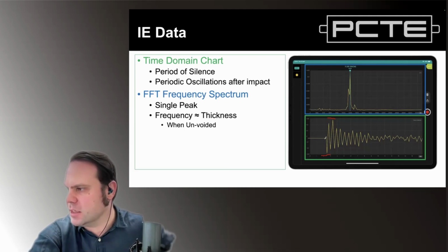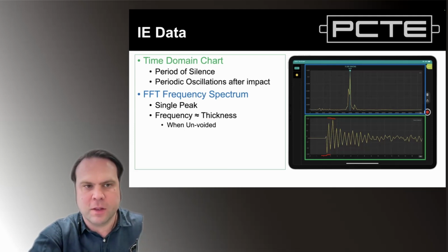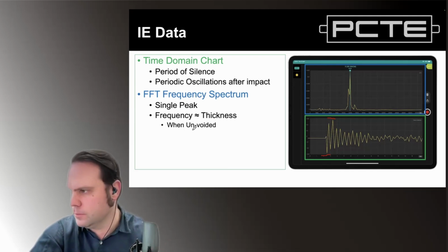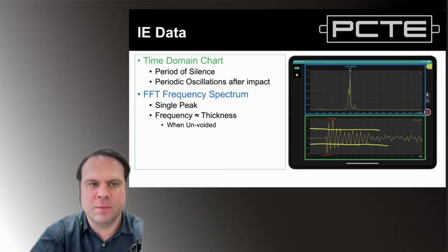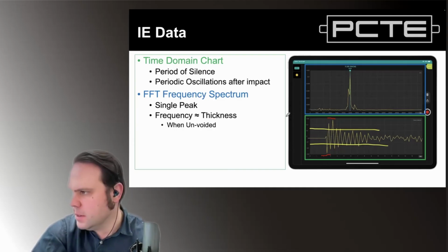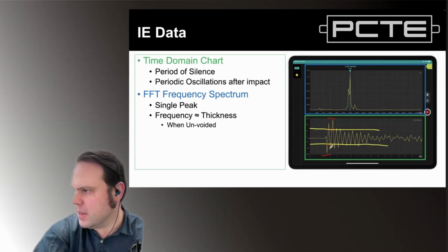It has the effect of essentially chopping off the result. So if I was to have an inappropriately set input gain on the results, and this was the minimum and maximum of the chart, what happens is the peaks, positive and negative, of the sound results get chopped off and flattened.